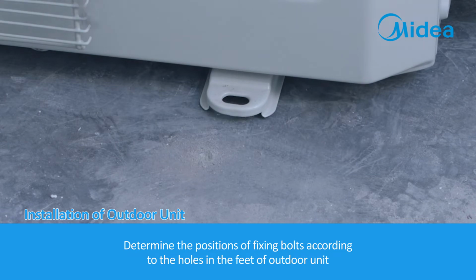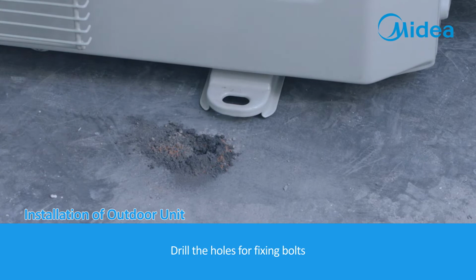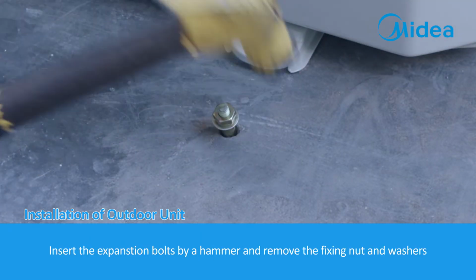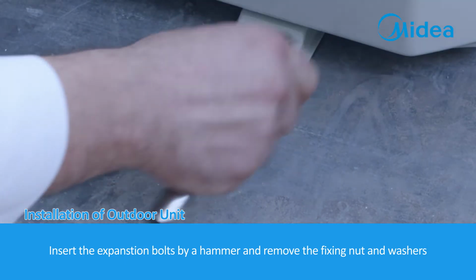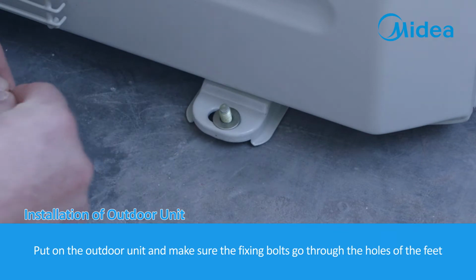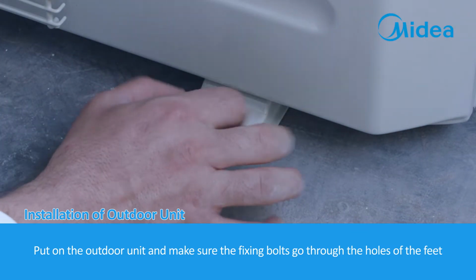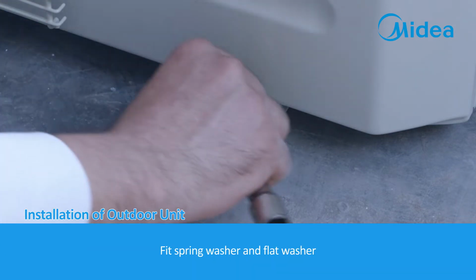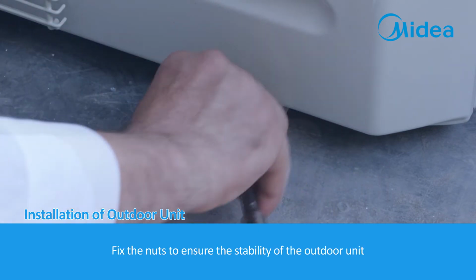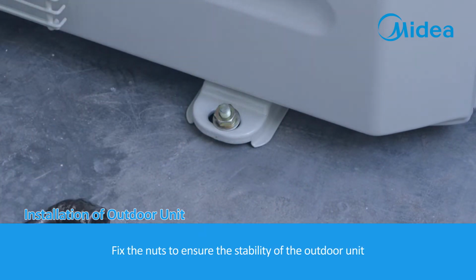Drill the holes for fixing bolts. Insert the expansion bolts by a hammer and remove the fixing nut and washers. Put on the outdoor unit and make sure the fixing bolts go through the holes of the feet. Fit spring washer and flat washer. Fix the nuts to ensure the stability of the outdoor unit.